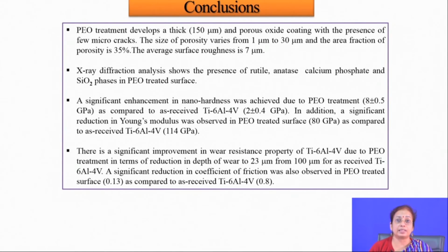In the channel there is plasma generation, because the inner channel region acts as a high resistance region and a very high amount of heat is generated there. Because of that, the underlying substrate gets melted, and that melted material passes through the channel towards the surface, and then again there is formation of oxide scale on the surface. Like that the cycle continues.